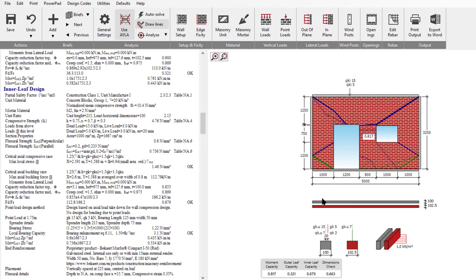Colors. Why have we got 2 colors of yield lines? Well, if you think of slabs, if you think of beams, sagging moments is what I would call them, sagging yield lines, and these are the hugging ones. So from this fixity, you're getting a fixity, fixity, and then fixity around here. You'll also notice the fixities don't go to the edges because it's looking at the lower bound solution, and we're finding that a weaker solution is when the yield line comes across here and it sort of cracks here. So there you go, that's your solution.